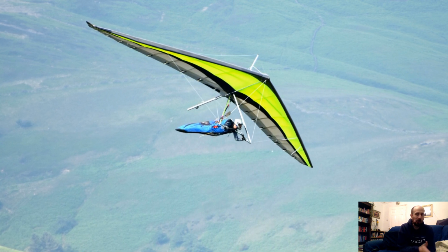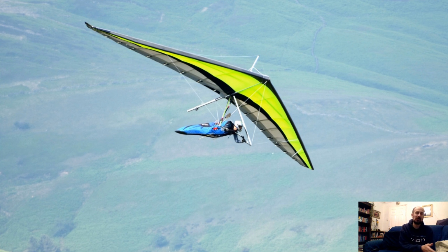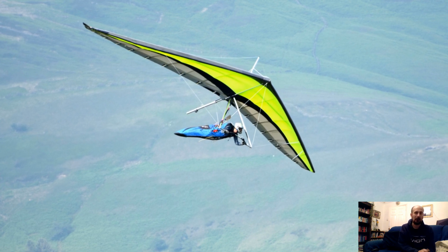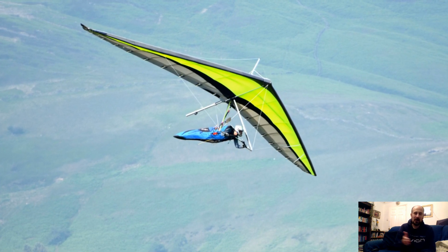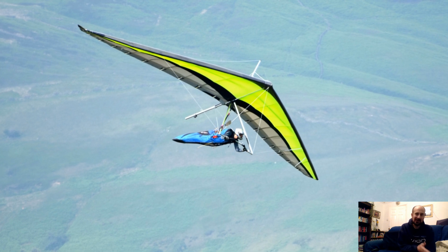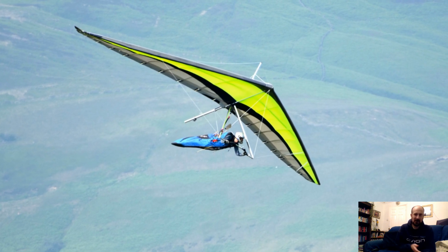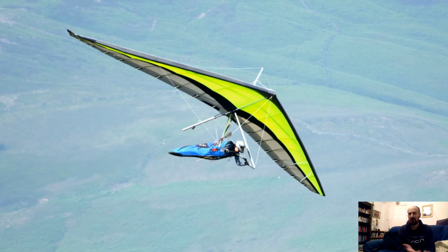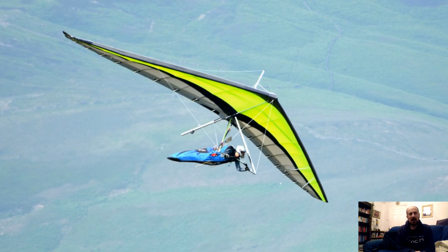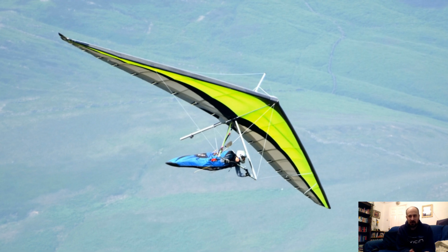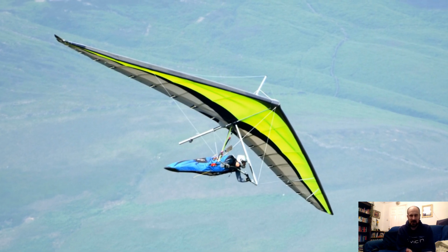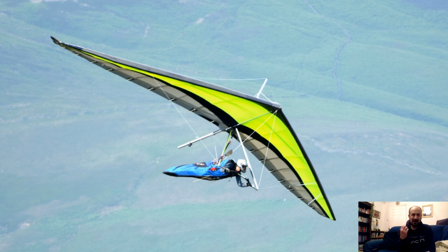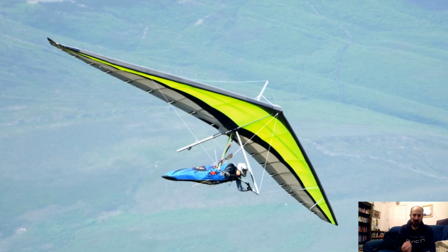Now, it's possible to have a perfect lift distribution and also to have a pitch stable wing, but it's really not easy to design that, especially designing it into a swept wing that also bends as the lift is applied to it. It needs some computational firepower to do that, and frankly, it also needs a lot of knowledge to do that as well.